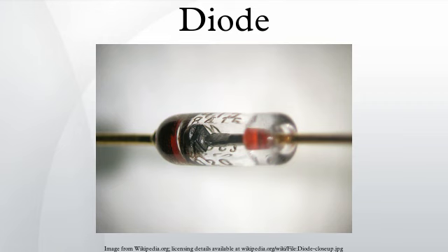At larger forward currents, the current-voltage curve starts to be dominated by the ohmic resistance of the bulk semiconductor. The curve is no longer exponential, it is asymptotic to a straight line whose slope is the bulk resistance. This region is particularly important for power diodes. The effect can be modeled as an ideal diode in series with a fixed resistor. In a small silicon diode at rated currents, the voltage drop is about 0.6 to 0.7 volts.